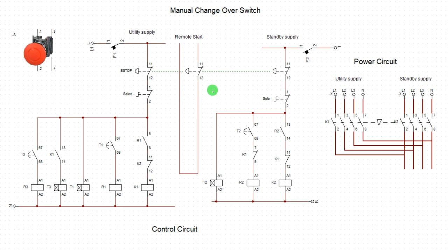Now, every digital panel also has what we call a cooldown function, cooldown duration. Although not all of them, very few do not have it, but virtually all of them have it. From the factory default setting, the manufacturer is aware that the end user might decide to use ATS to control the genset control panel. So they made a provision for ATS enable, and they also put a cooldown duration for shutting down the genset with timing, apart from ATS, that function is enabled from the end user.